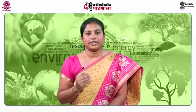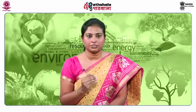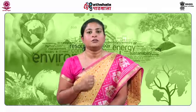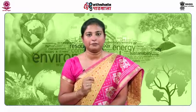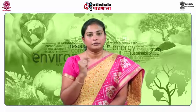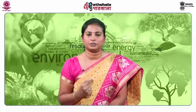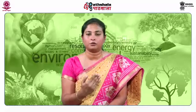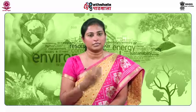So, a landfill bioreactor is an engineered landfill developed to speed up the process of waste degradation and promote environmental protection through proper gas and leachate management system. Waste stabilization occurs within 5 to 10 years of implementation, but it requires a minimum of 35 to 40% moisture to increase the rate of waste degradation. At times when leachate is not sufficient to maintain the required moisture content within the landfill bioreactor, you can opt for other liquids like storm water runoff, wastewater treatment sludges, etc.